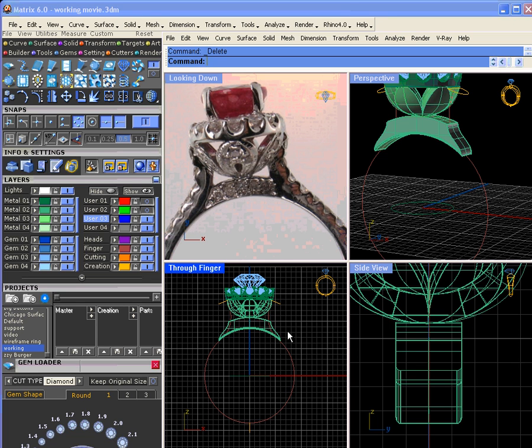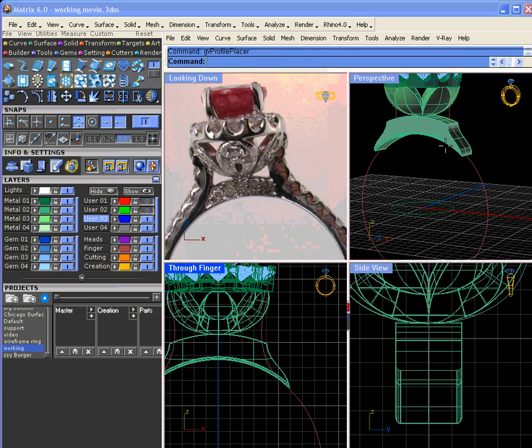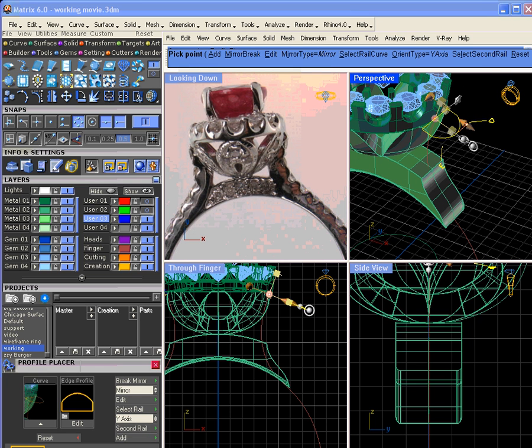Okay, so I wanted to fix this up because I want it to stay thick down here like this one does. It's fairly thick here, and then it gets thin real quick. And this felt pretty heavy up here at the top. I mean, I want it to kind of fade into this part here. So let's go ahead and go F6 MSR, and we'll go ahead and make this thinner.